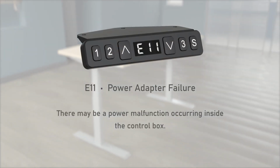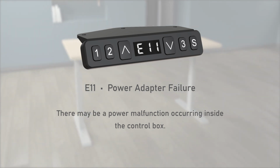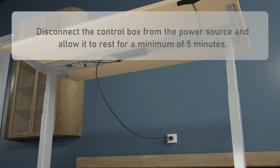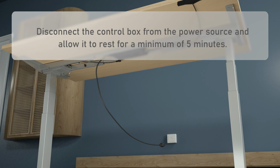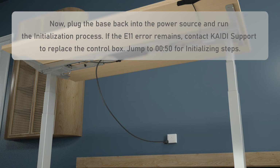E11, power adapter failure. There may be a power malfunction occurring inside the control box. Disconnect the control box from the power source and allow it to rest for a minimum of 5 minutes. Now, plug the base back into the power source and run the initialization process.